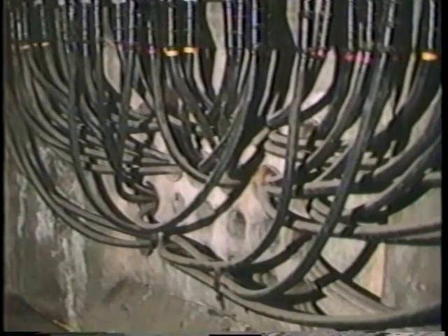This condition is more likely to occur where voltages are 12 kV and higher, and also where the line capacitance is high, for example, with long lines or where cables are used. When you think of all of the variables in the circuits, this subject of ferroresonance is obviously highly complex, but it is essential that we understand the principle, because we shall be meeting this term in future tapes when we discuss specific installations.